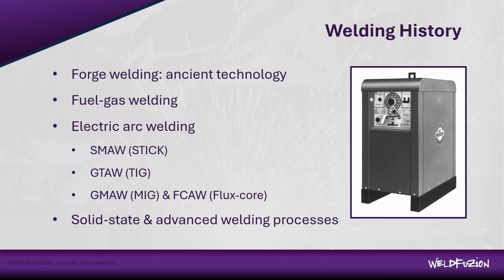Solid state and other advanced processes such as laser welding, friction stir welding, and even resistance welding have all been developed to employ emerging technology to solve old problems and overcome the limitations of earlier welding methods. Each process is an engineered solution to a problem, given the constraints of the time. And that's not to say that new processes are always better or that old processes will automatically disappear, right? I mean, stick welding is one of the most predominant welding processes in the world to this day, and it was developed in the early 1900s. And you see it still being used despite the benefits of MIG welding.